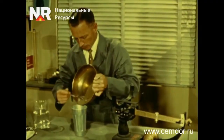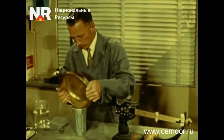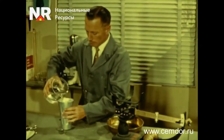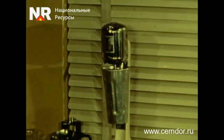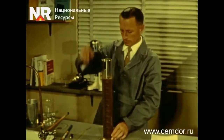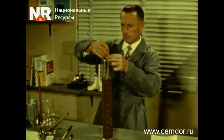The residue on each sieve is weighed. The distribution of the finest soil particles is determined by the hydrometer method. For this, the residue is mixed with water using a high-speed mixer. Based on each measurement taken with the hydrometer, the total soil content must be calculated using a special formula.